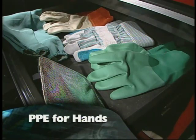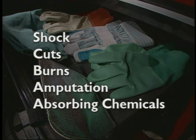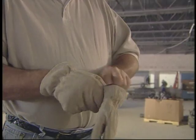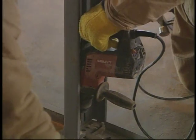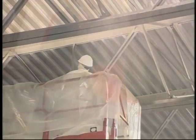PPE for hands protects against shock, cuts, burns, amputation, and absorbing chemicals into your skin. Leather, mesh, or canvas gloves are the most common type of PPE used at construction sites. They must fit well. Inspect them regularly for damage and wear. Take care when using gloves with tools and around equipment so your gloves don't get caught.